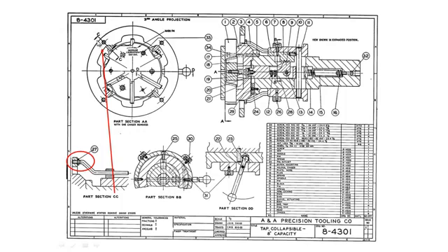One thing to note is that this is drawn on an older standard, so you can see these arrows are coming away from our section line. If we were to draw these, we would rotate them 180 degrees so the tip of the arrow is on that line. Now, if you look at our projection that is coming off orthogonally over to here, you can see we've got that nut there again.